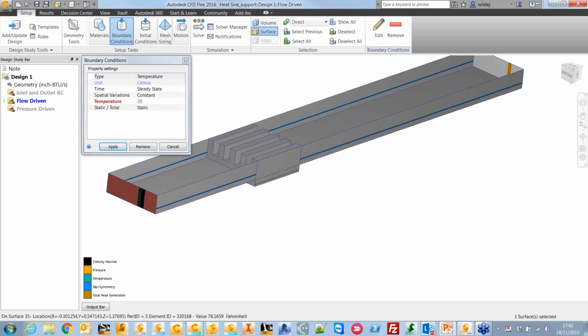One thing that I think is worth mentioning, John, can you hit the type drop down for boundary conditions? Yeah. So if you're looking at those top boundary conditions, the velocity, the volume flow rate, and mass flow rate, those are all averaging an even velocity across that surface. I thought that's worth mentioning because we do have the fully developed option now.